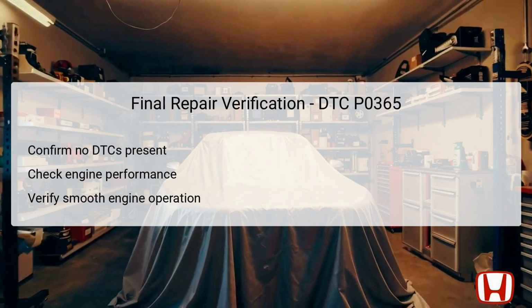Additionally, ensure that the vehicle starts without any issues and maintains a steady idle. Lastly, conducting a short test drive while monitoring for any warning lights is advisable. If the vehicle exhibits consistent performance without re-triggering the fault code, the repair can be considered successful.